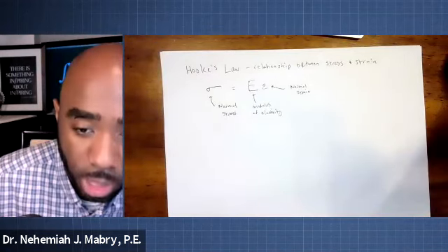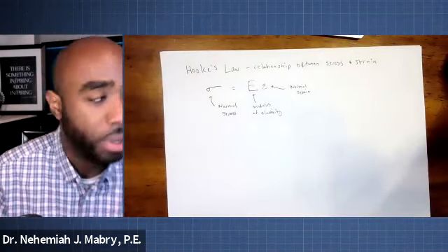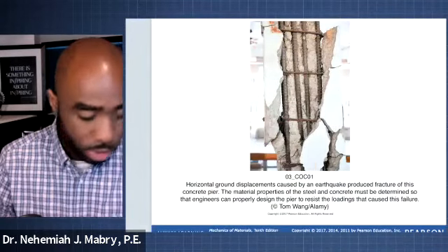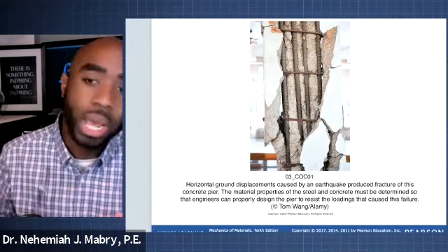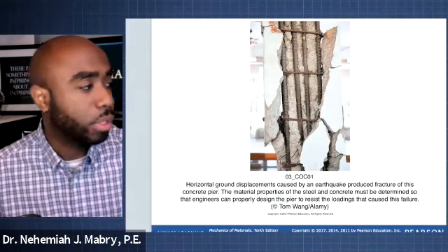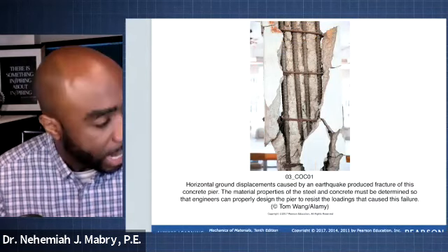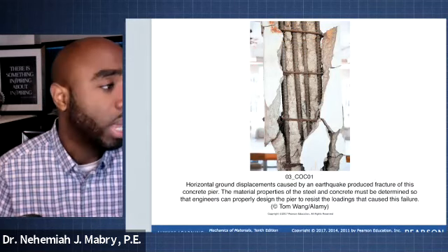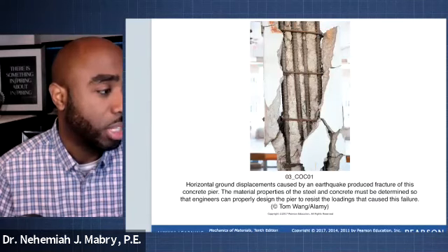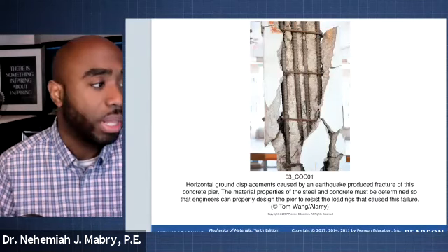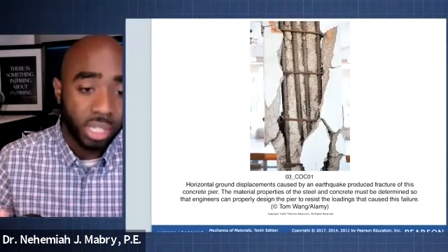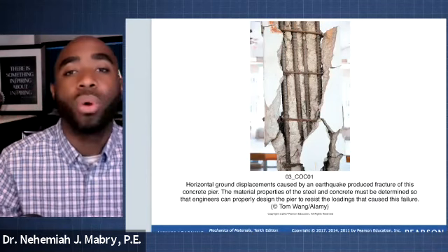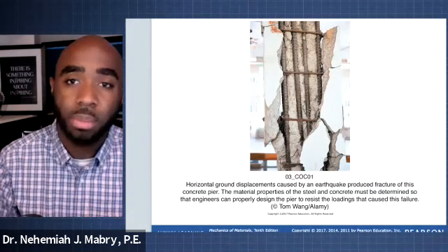Now, for a second, we're going to take a pause here with the document cam and look at our screen. Here we have a picture of reinforced concrete. Inside of this reinforced concrete are steel bars, and steel is put inside reinforced concrete to give it additional strength. Concrete is very strong in compression, but steel is strong in tension. It also has a little bit more give, as we're going to talk about, as it begins to fail.